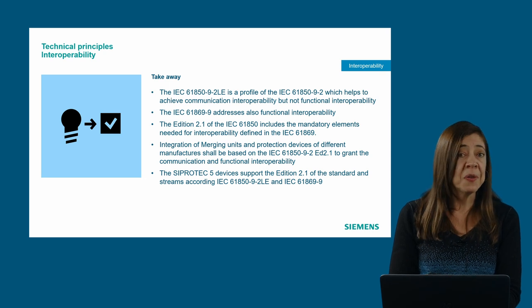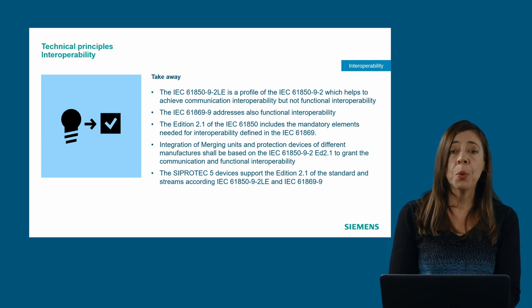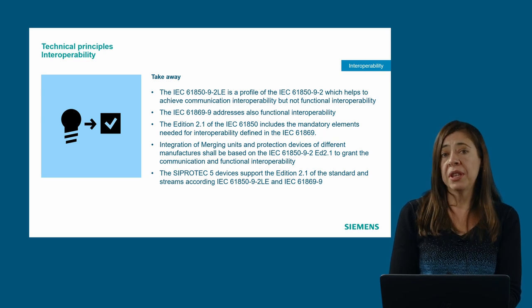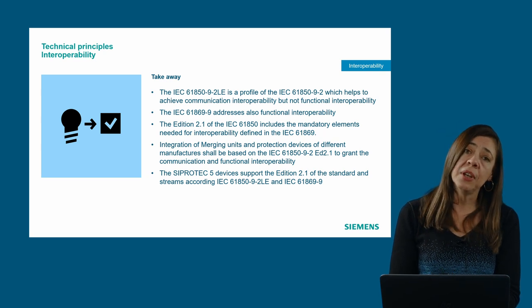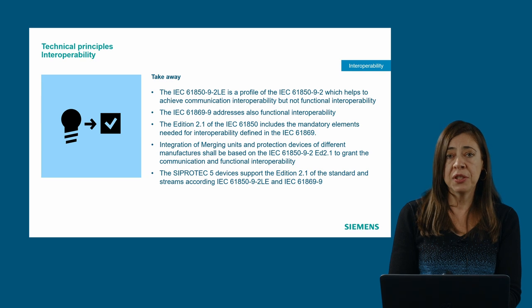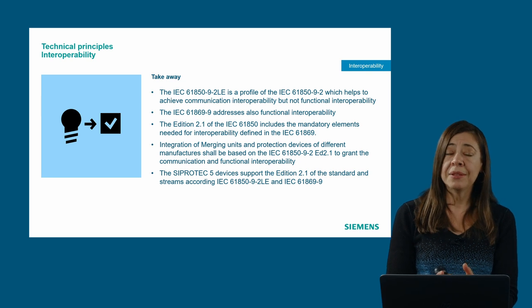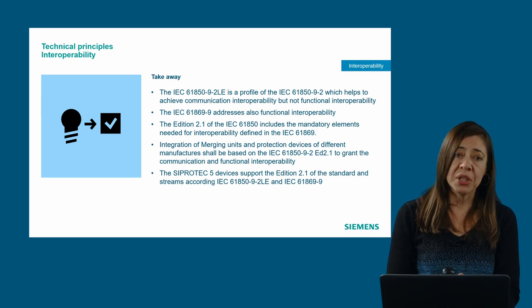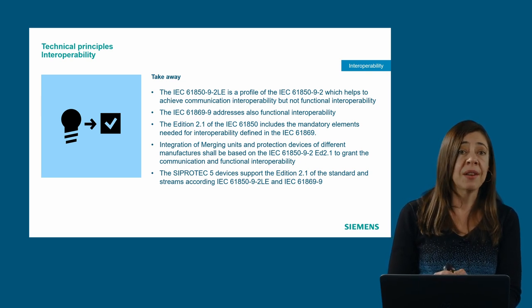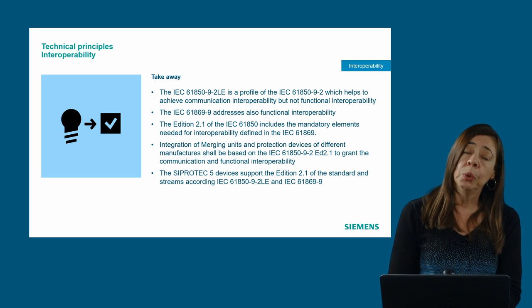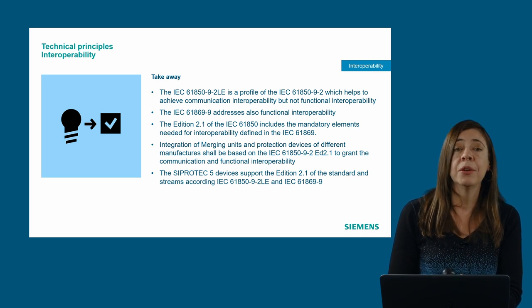The SIPROTEC 5 devices support this edition 2.1 and can also support both types of streams, the Light Edition stream or the flexible streams according to the IEC 61869-9. So remember, the third key point of the technology is the use of international standards to fulfill this interoperability.